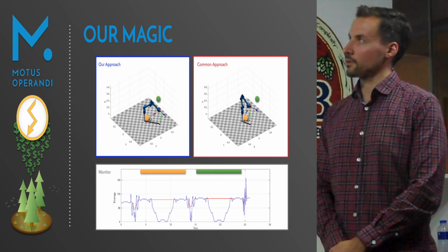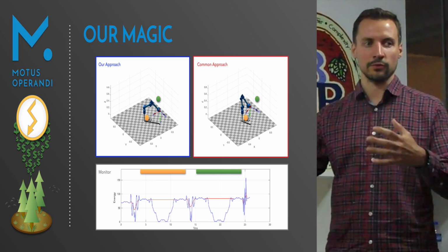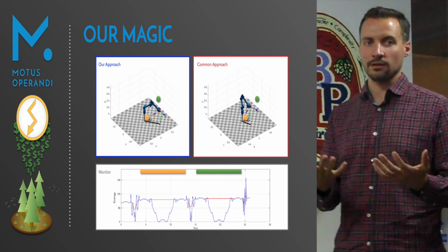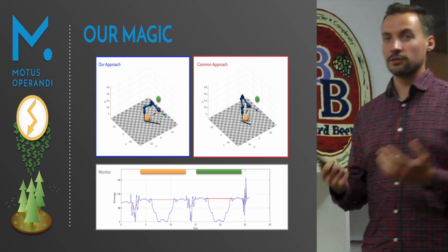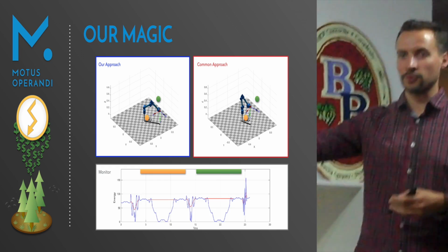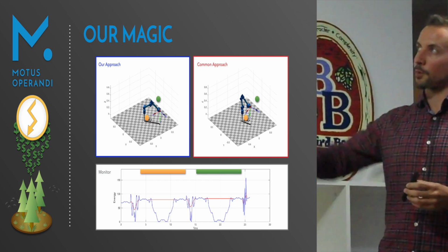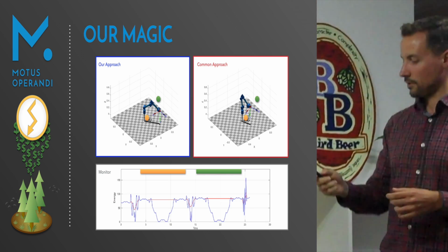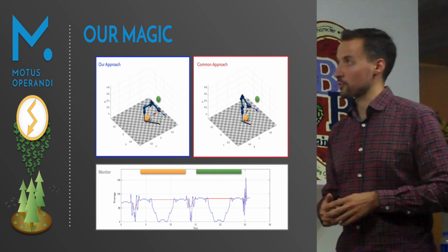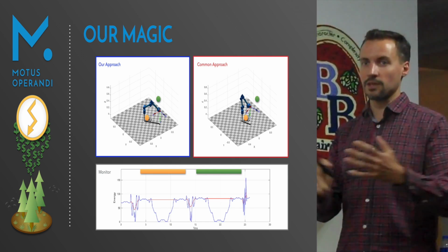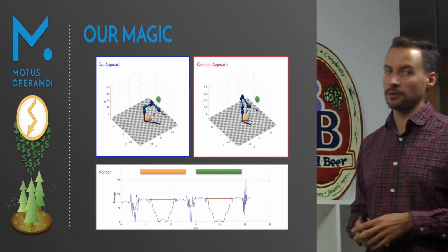Now what you see, normally, the robot puts the object into machine 1, and then the machine has to process the part, so the robot needs to wait. Normally you don't consider this as something you need to program. You just put the part in and you wait. Done. So the robot is not doing anything for 6 seconds. But it actually consumes electricity. It's just sitting there stretched out, and you should do something better. So in this case the robot goes up into an equilibrium position where it consumes almost zero energy, which you can see here. At this very point it's almost zero. It's not completely zero, of course, but it's a very low level of energy. So for this whole application we keep the same productivity, evidently, and we can save up to 30% energy just by implementing different motion.